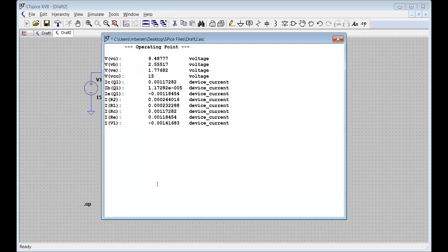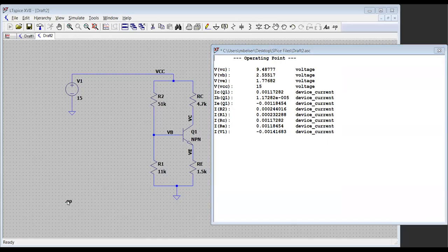So we hit plus here. It shows it here, and then we run the simulation, and here's the data. So let me slide over here a little bit. And here's one thing I liked about LTspice that was a little weird for me coming from the Cadence tools. With the Cadence tools, you had another window or a file where you set up your simulation commands. LTspice puts your simulation commands right on the schematic itself. So there's not another file you need to go to set up. You just click it through the menu. So here's our operating point.